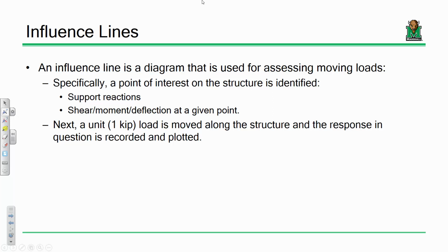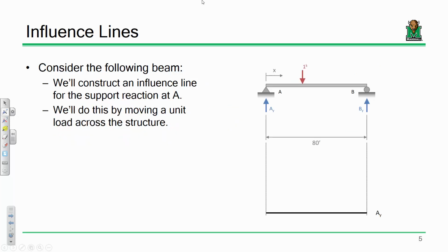That's very common within bridge engineering. So what I mean by 10th points is that if you have a 100-foot bridge, for instance, you will determine moments and shears at 10 foot, 20 foot, 30 foot, 40 foot, 50 foot, 60 foot, 70 foot, and so forth, at every 10th point. If it's an 80-foot bridge, 8, 16, 24, 32, and so forth. Make sense?